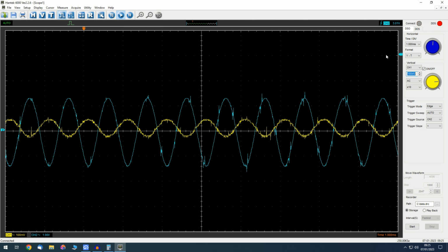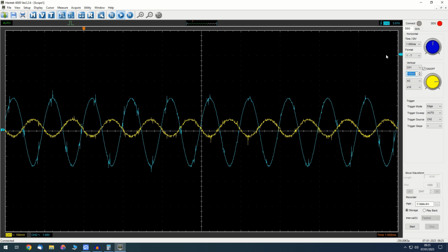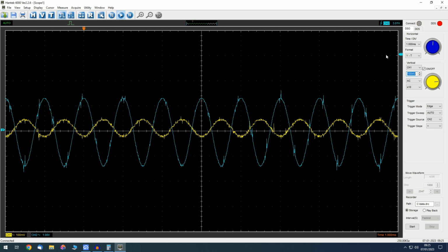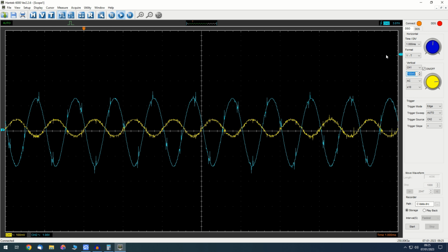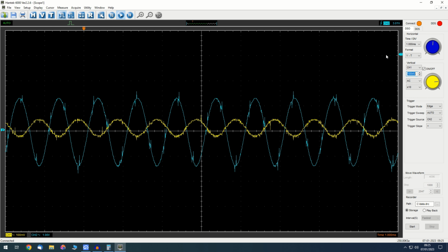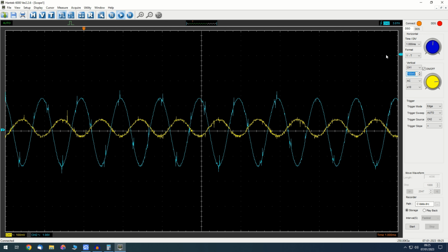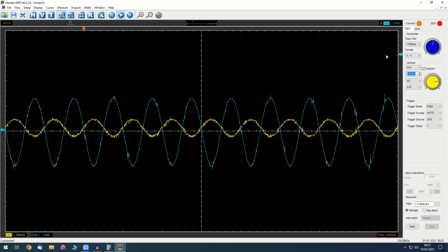And so the noise, I don't know what that's from, it could be from anything, but that's not part of the amplifier itself. It's from the other equipment around here in the computer and things, or with the USB, something like switch mode devices in the USB power. Anyway, so that's with a 33 ohm resistor,